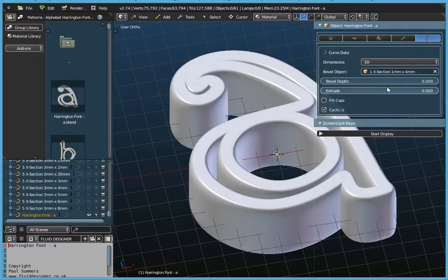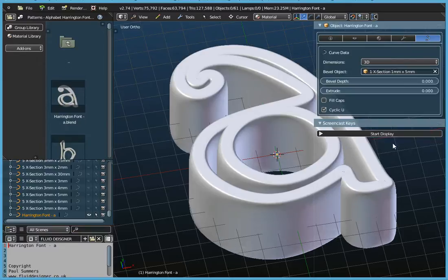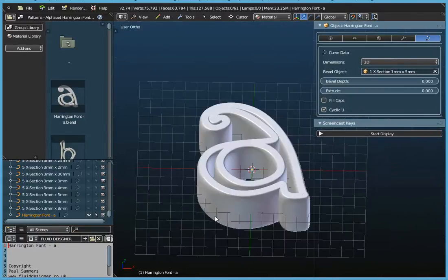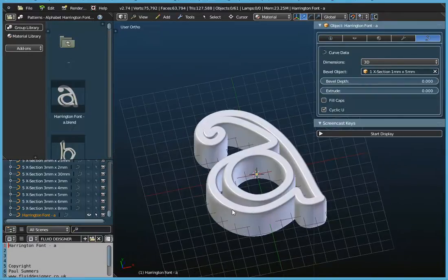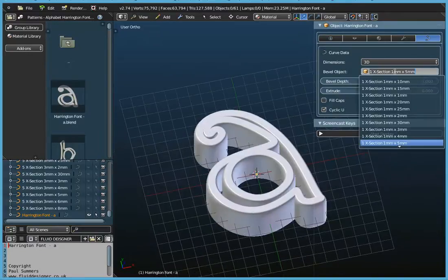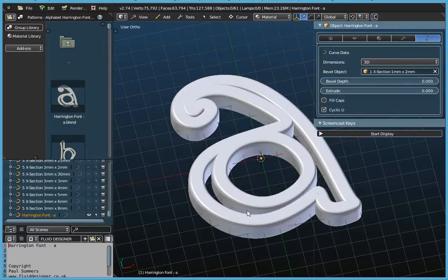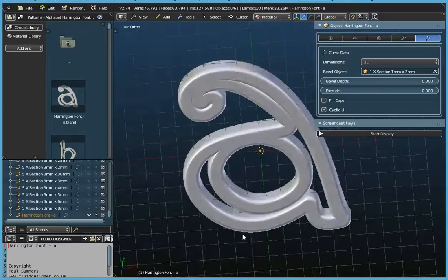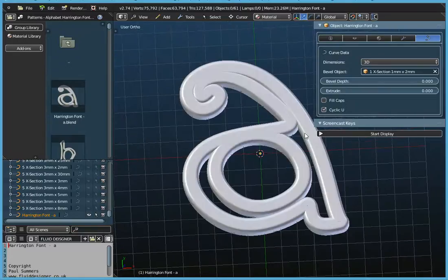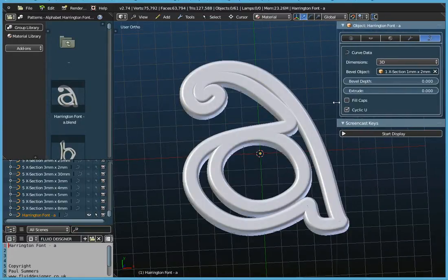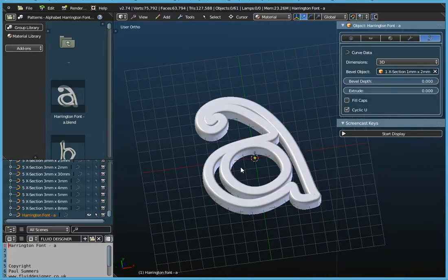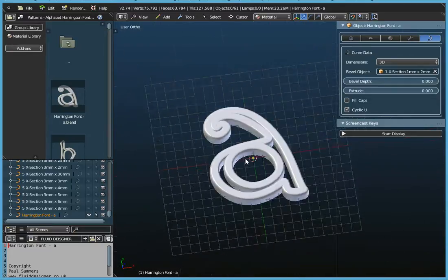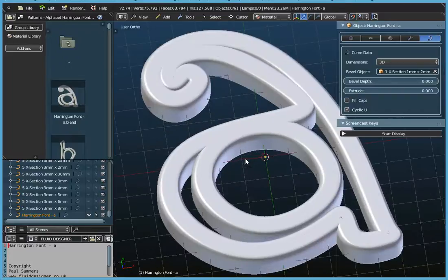Now what you've got to take into account, if you're going to make an earring out of this, the thicker you make it, the more material is used, the heavier the object becomes. So I'm going to return it to a thickness level of 2 millimeters. That keeps our object nice and light. Okay, so that's how we could change the thickness of this object. And I'm just zooming in and out here by again scrolling the center mouse button.